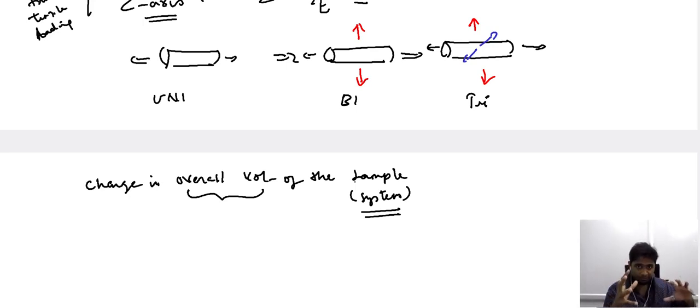So instead of representing the response exclusively associated with a specific direction, we will be considering the sample as a whole, the entire volume of the sample, and we will try to arrive at an expression for how the volume changes for a given loading condition. We will not be starting with the uniaxial tensile loading, but with the triaxial tensile loading. Since we have already been exposed to triaxial tensile loading, we will start with the convoluted representation of things, and then narrow it down to our specific condition,